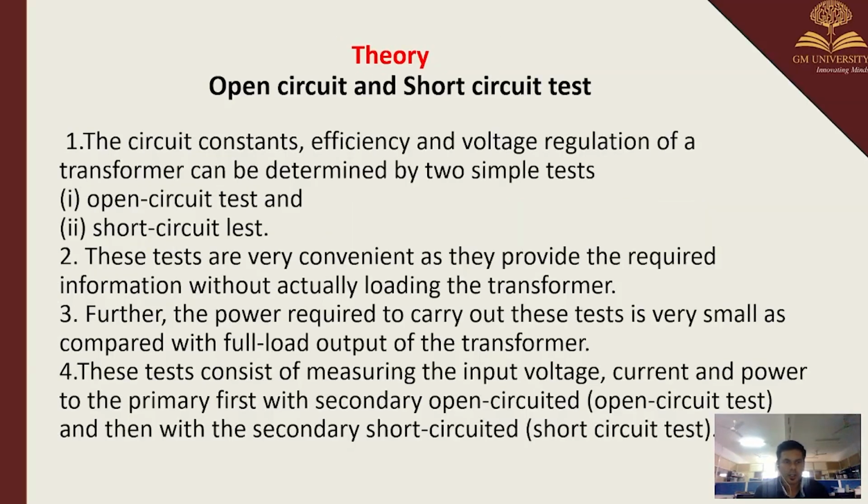The theory is, in this we are conducting two tests, that is the open circuit test and the short circuit test. In the open circuit test we are determining the core loss, or iron losses, of the transformer. In the short circuit test we are determining the copper losses. From this we can ultimately determine the efficiency and voltage regulation of the transformer.